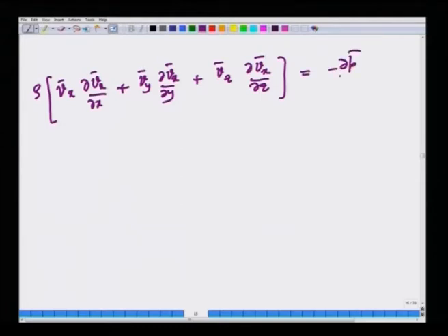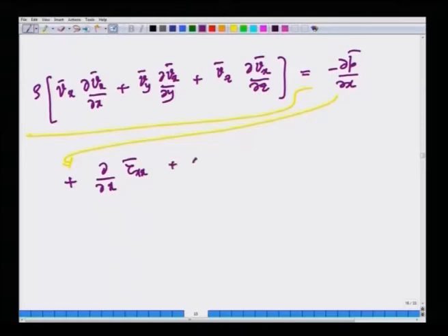So the pressure term, plus, I am going to continue from here, plus now you have these various stresses, partial by partial x of tau xx. These are simply normal averages, because they are linear terms. If you average a quantity, you will just get its average, because the integral sign and differential sign can interchange. Now, there are other terms that we could not neglect. So we have to write them here. They come with a minus sign, because they come to the other side of the equation.